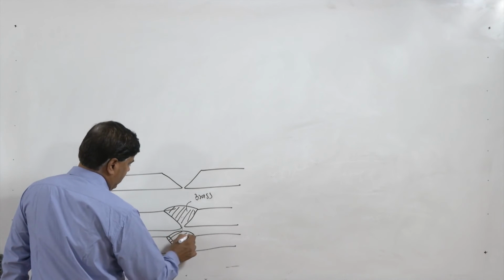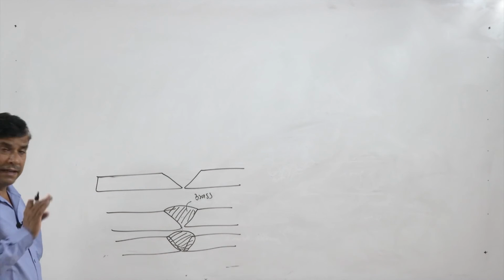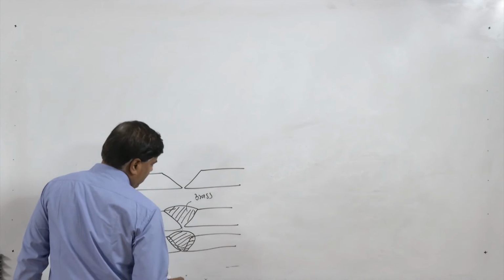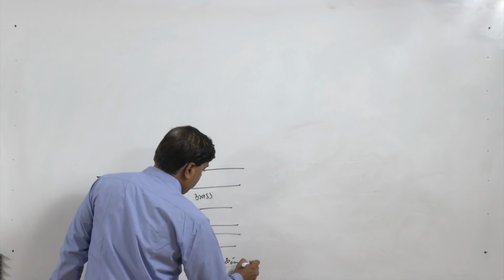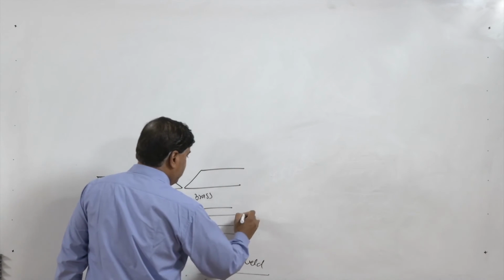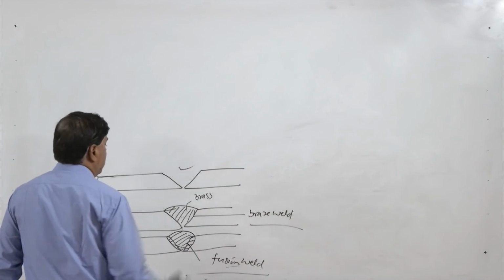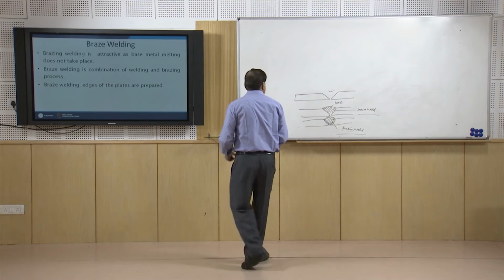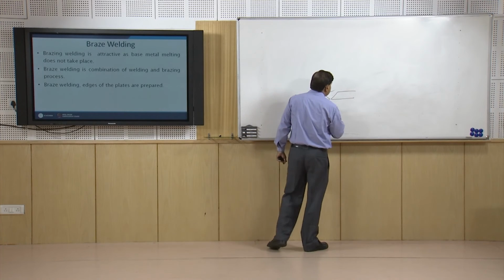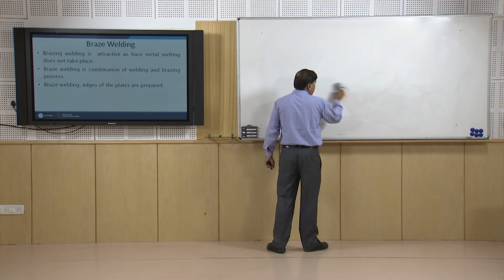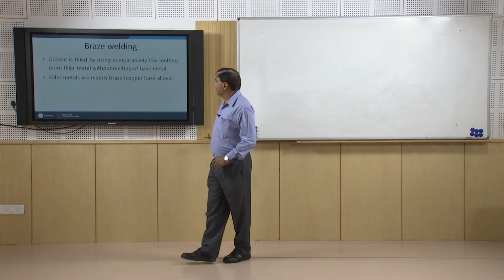So, here the straight edges which were prepared by machining are eliminated, they are brought to the molten state, and this is typical in case of fusion welds. This is in case of braze welds, and this is the V groove prepared for developing either a fusion weld joint or a braze weld joint. So, in case of braze weld joints, the edges prepared remain intact, only the filler metal is brought to the molten state and the melting of the fin surfaces does not take place.